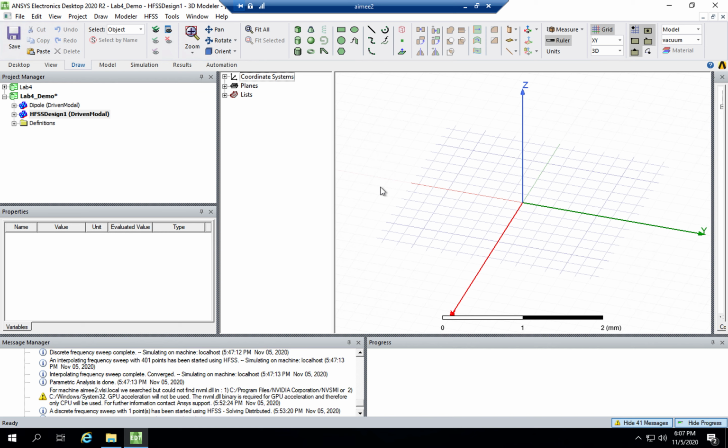Normally antennas are designed so that their maximum gain is in the Z direction, but this is just a convention. You don't have to do it this way, but that's why when I design the waveguide now, I'm going to design it so that it's pointing up towards the Z, and the horn will flare towards the Z. But you could also do it in the Y axis. It's really up to you. The results should be the same.